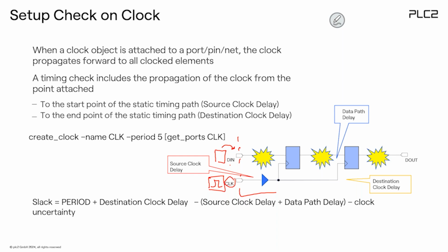Then all the other stuff like delay, the combinatorial delay on the nets, the clock-to-output delay here, everything else is known by Vivado because the implementation is done, all the delay information is already there, and now Vivado starts the analysis. It looks difficult, but you don't need to. You can really take a piece of paper and just calculate the values, but that's actually what Vivado is doing for you.